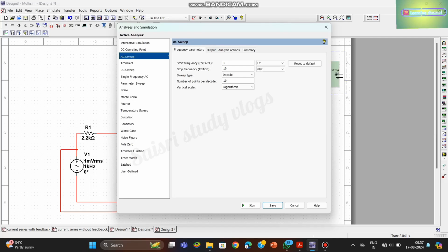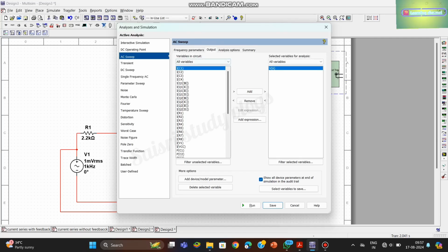So in order to select the voltage, here I have selected a voltage. How do you select it? Just click on the oscillator wire which you have connected for the output. There you can get the net value. Here you can see, just click on the voltage wire and there you can get the number. That number you have to give and then click on apply.